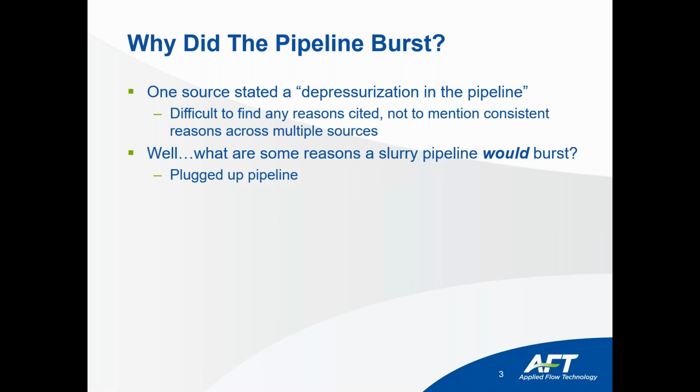Obviously, like I just mentioned, if the pipeline gets plugged up, it just starts building pressure more and more. You're deadheading against that plug from your pumps, and that's going to be one thing that will cause your pipeline to burst.